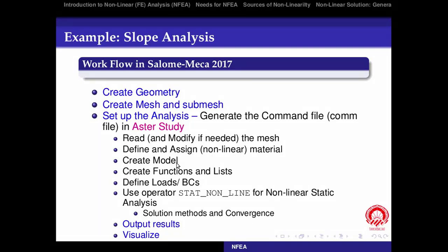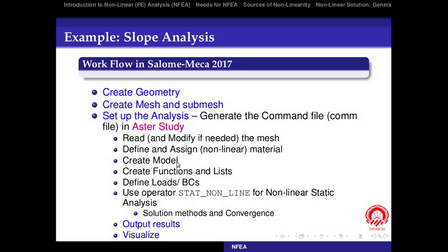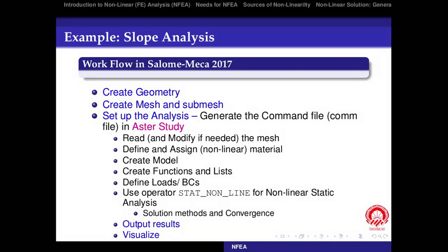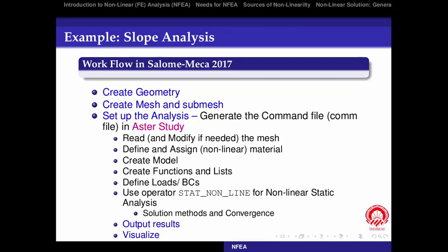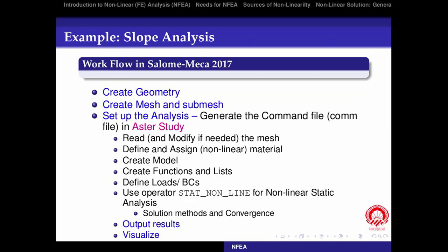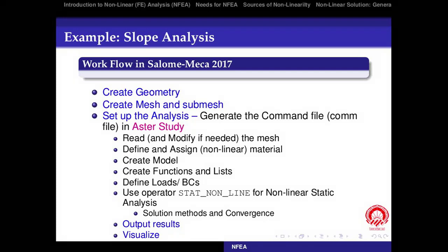Then for nonlinear analysis, as we know, the load and deformations, everything are functions of pseudo time in case of static analysis, or functions of real time in case of dynamic analysis. So we need to create some functions expressing the load as function of time, and we need to create a list of time stations, time instants at which we want the analysis to be performed.